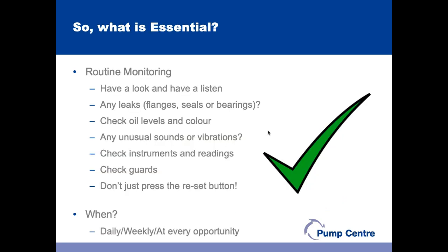So what sort of activities are essential when it comes down to pump maintenance? The first category I've got here is what I've called routine monitoring, which essentially is just having a look and having a listen, looking for any leaks from flanges, seals, or bearings. If the bearings are oil lubricated, what do the oil levels look like?